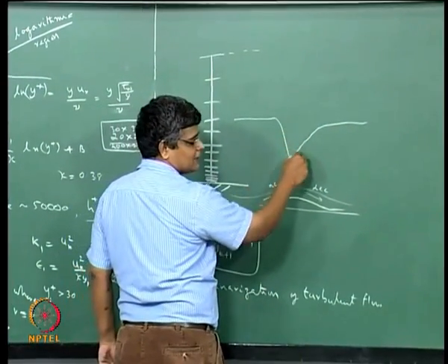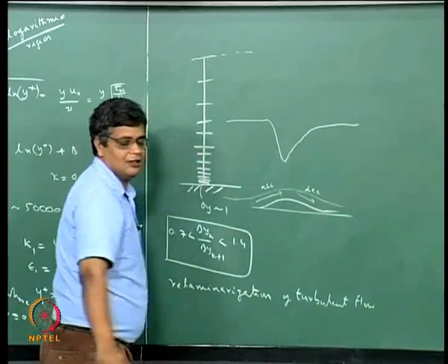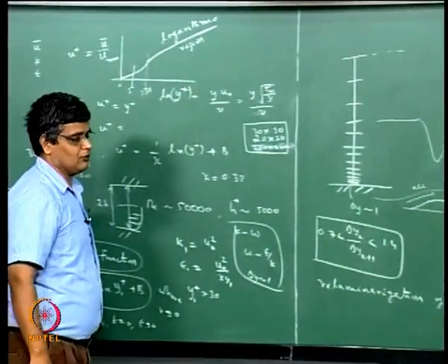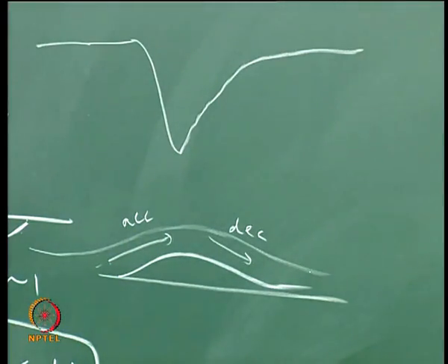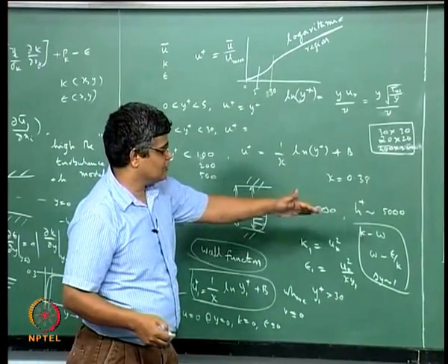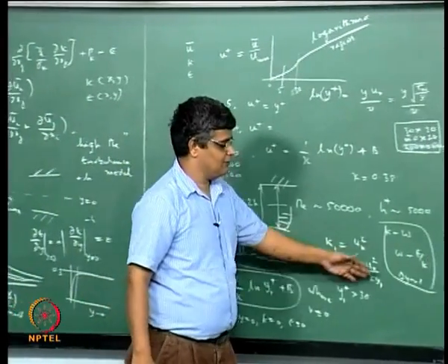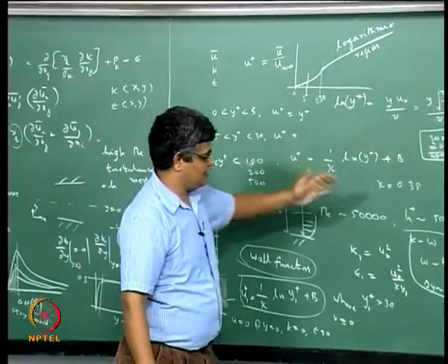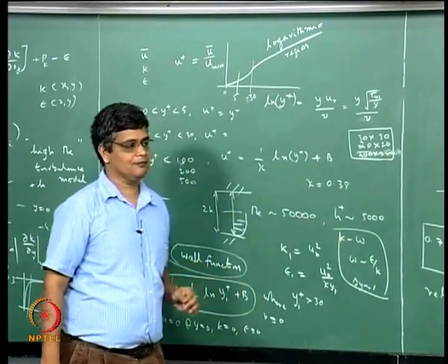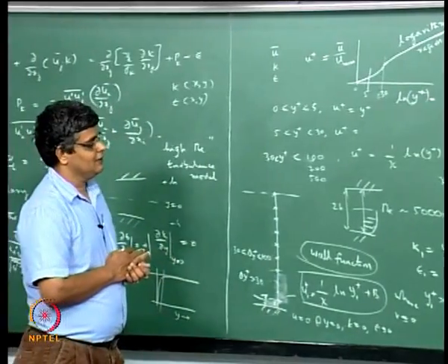So, this drop in the heat transfer coefficient, the Nusselt number, is associated with the relaminarization of the flow, and if you want to capture those kinds of effects, then you have to resolve the turbulence right up to the wall. So, in such a case you may have to use low Reynolds number versions of these models, or the k omega type of models, to get these special effects.